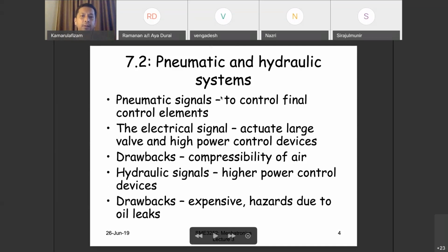A pneumatic signal is the air in a pneumatic system. Just put it in your head: air. It is a system that works based on air, like the hand pump you used earlier to pressurize the submarine system. Those are pneumatics. And when you pump liquid, you are working with hydraulics. So pneumatic signals refer to the fluid, the air, and hydraulic signals refer to the fluid of oil or water, any fluid.